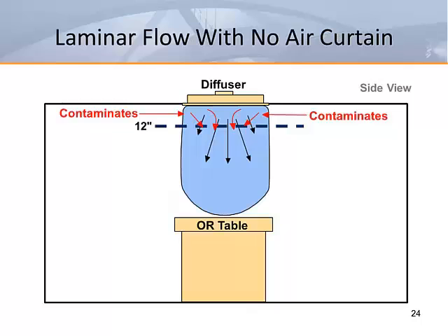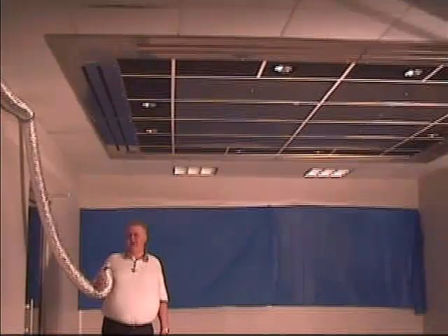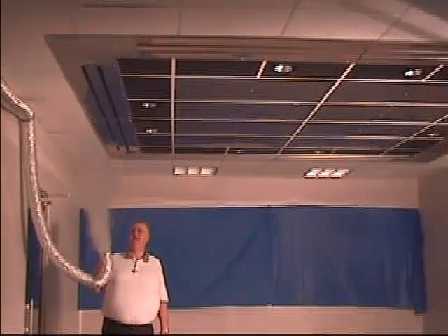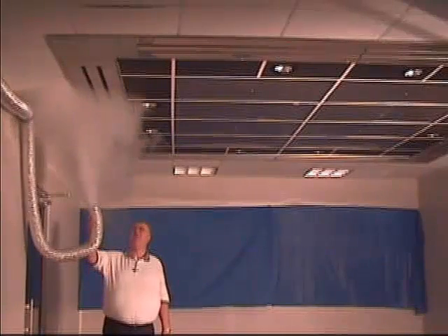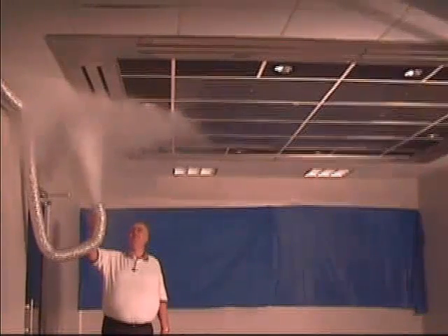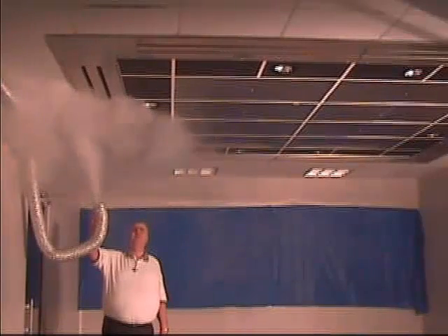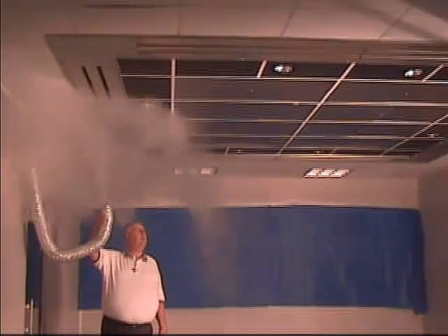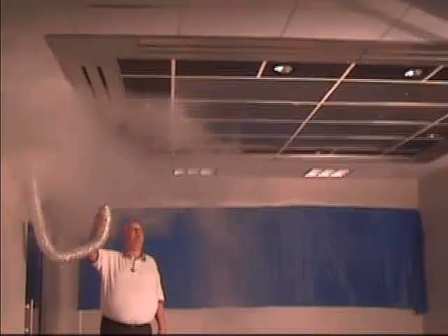This elevation view, illustrating the air flow from the non-aspirating outlets to the surgical table, illustrates the air pattern as we would expect it to happen. The reality is that the lightweight airborne contaminants near the ceiling can be induced and carried into the air supply to the patient. In this smoke video, we can see how the lightweight smoke, when introduced into the room outside the sterile field, is induced into the pattern along the ceiling and is carried to the patient in the center of the airstream.